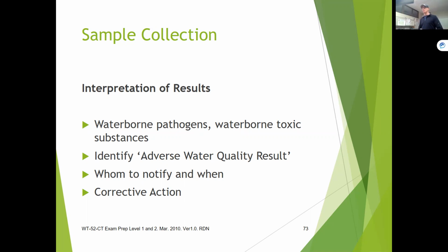Also important is to know your system. If there's going to be issues with your system, know whether you can shut this reservoir down, clean it and get it back online, or disinfect, or whether this affects your whole distribution system or just a small portion of it. So always make sure that you understand how your system operates and where the sample came from. Always look at the science, because I can't stress that enough.